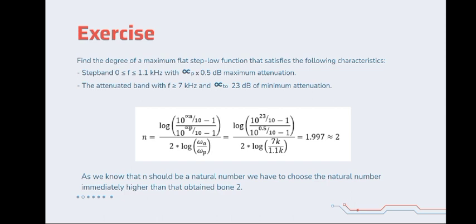A 1.1 kHz passband with a maximum attenuation of 500 millidecibels. Also a stopband at 7 kHz with a minimum attenuation of 23 decibels.